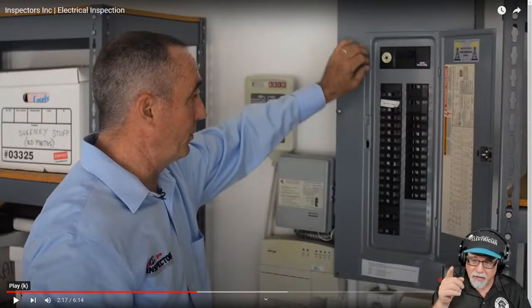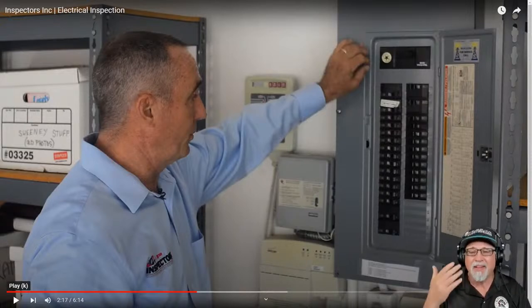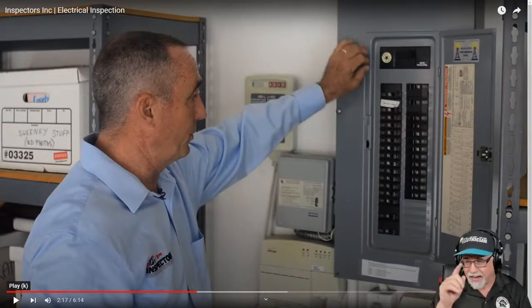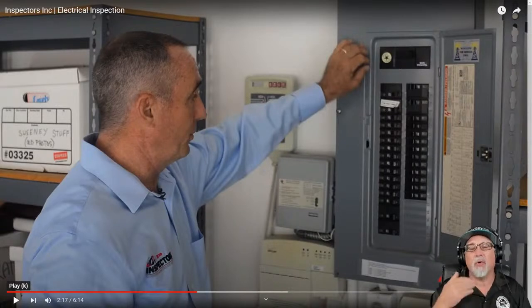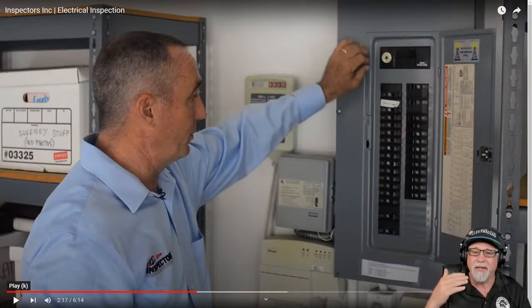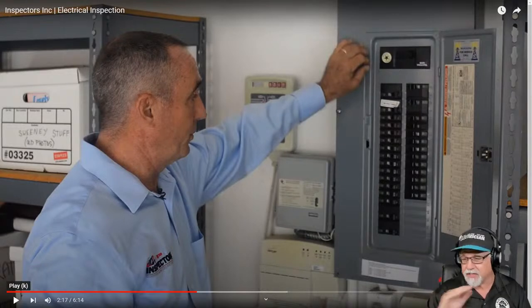And remember that main breaker provides short circuit, ground fault, and overload protection for everything on the load side. The only protection it offers for the conductors upstream, through that meter and everything, is overload, because obviously that breaker has an amp rating and it's going to limit the amount of load. That's the only protection upstream. From that main breaker down, everything else gets load side protection: short circuit, ground fault, and overload. But nothing on the line side, only overload that is inherent to the rating of the device. Okay, just little things to remember.